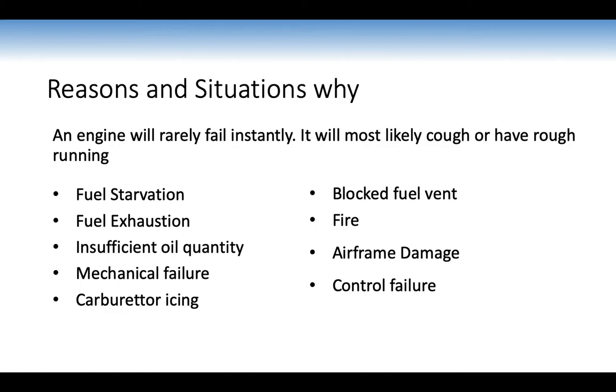So reasons and situations why. An engine will rarely fail instantly. It will most likely cough or have rough running. Some of the reasons are fuel starvation and fuel exhaustion. Fuel starvation, there's fuel but it can't reach the engine. Fuel exhaustion means we've simply run out of fuel. There's no more fuel left at all.